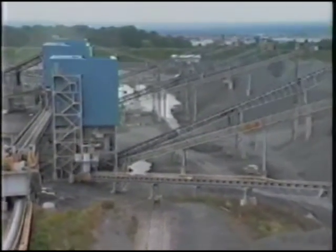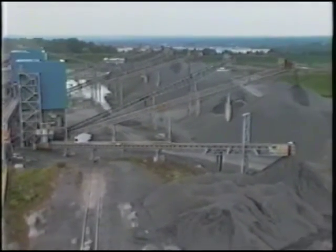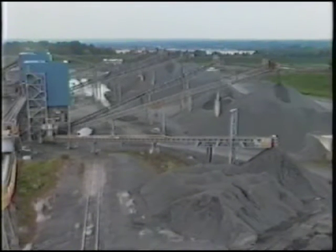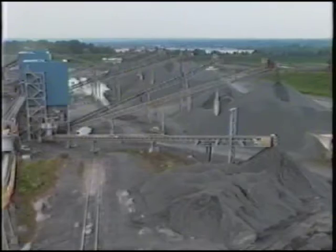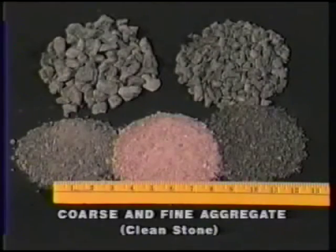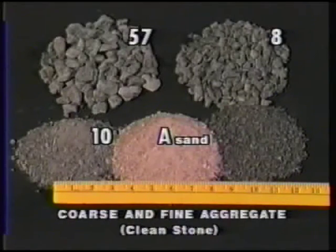In most cases, the tertiary circuit represents the final crushing, screening, and sizing of aggregate products. It is during this stage of the operation that the material is sized and separated into various coarse and fine aggregate products. These materials are generally referred to as clean stone or coarse aggregate sizes. Coarse aggregate sizes number 57 or number 8 and fine aggregate size number 10 and gradings A and B sand are examples of such products.